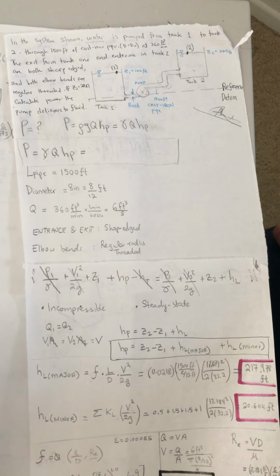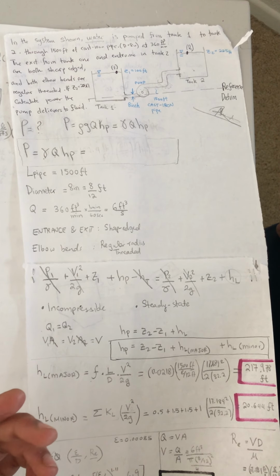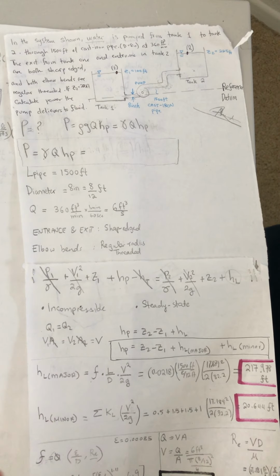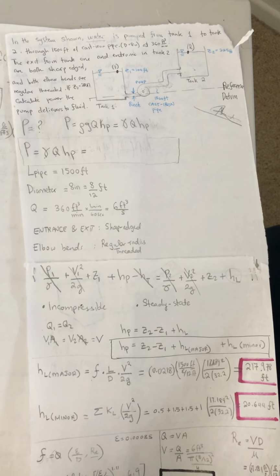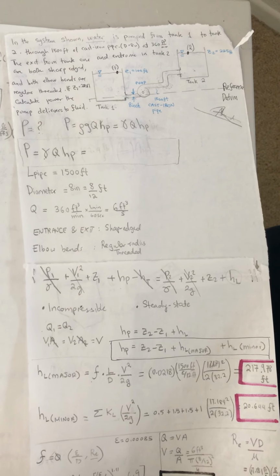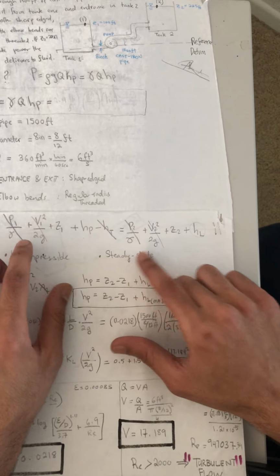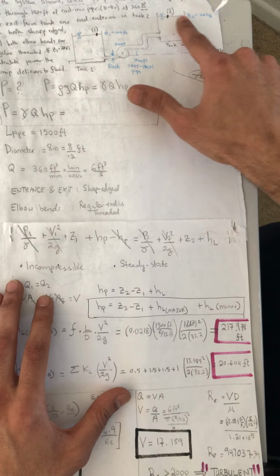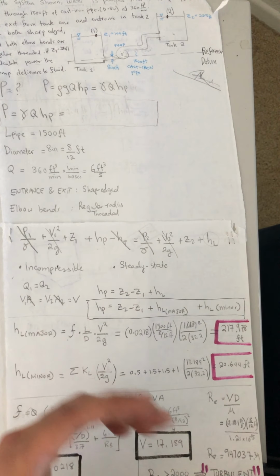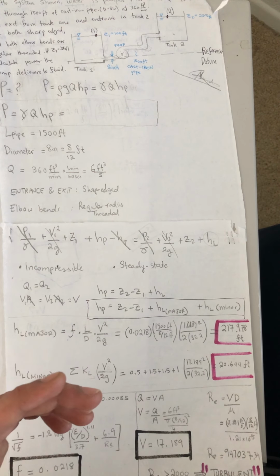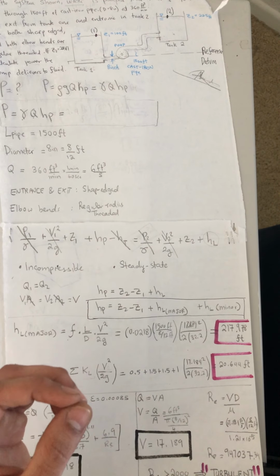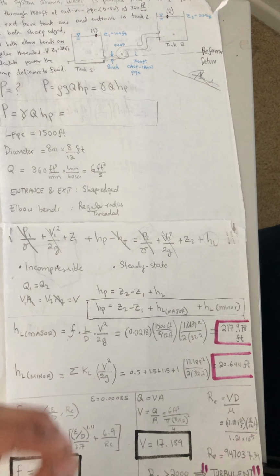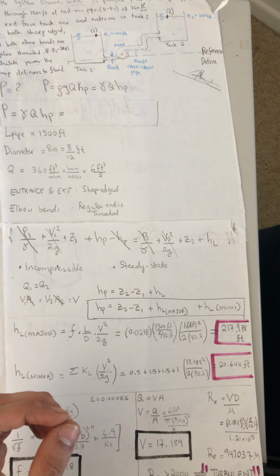We said that the head gain of the pump is calculated using the Bernoulli equation that considers the head losses and the head gains. And we wrote our Bernoulli equation. And then we identified our two locations in our system. Those two locations are selected in such a way as to be able to specify the maximum information required.